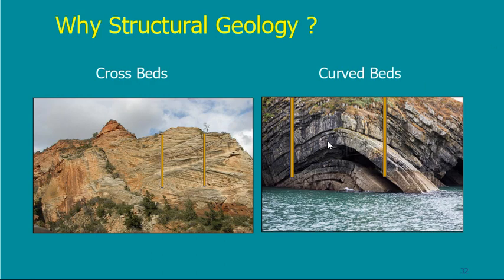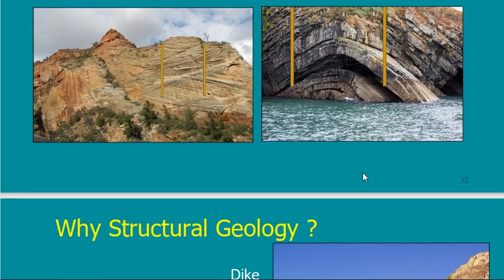It may be curved upward as an anticline, and it may be curved downward also. So if I am in doubt, I should add a borehole in between. Adding a borehole in between will tell me exactly what is the shape of the rock at this location.